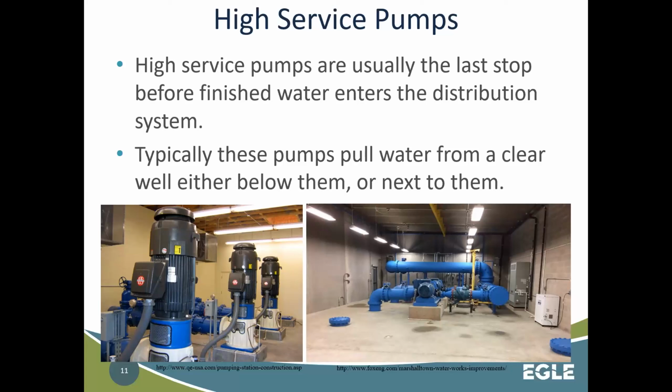Again, this is typically the last stop before the finished water enters the distribution system, right? We're pumping water up to the towers. We're pumping water out to the reservoirs and pumping water out to the customers as well. Typically, these pumps pull from a clear well which is either below them or next to them.